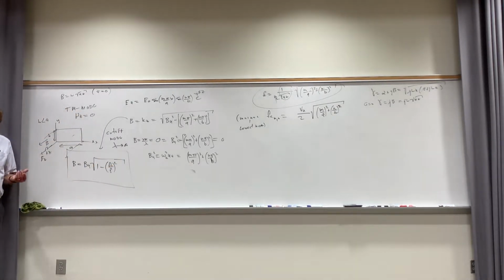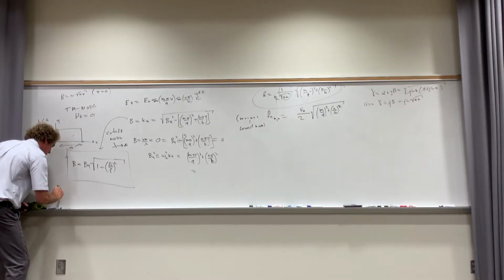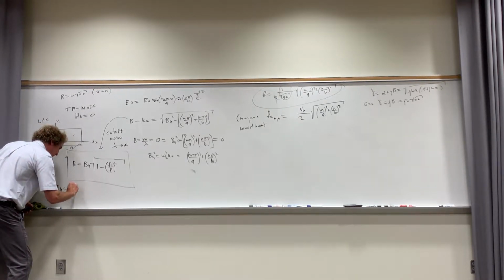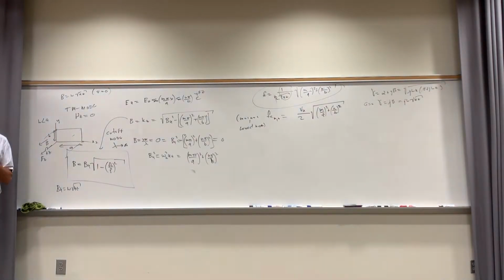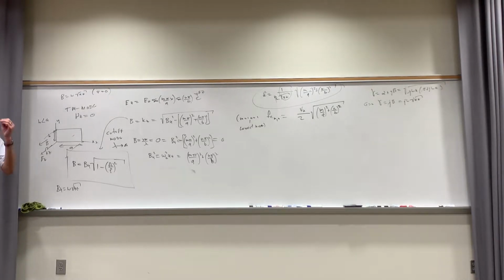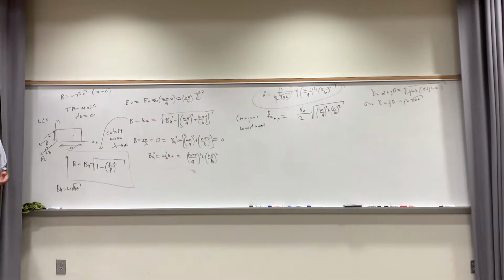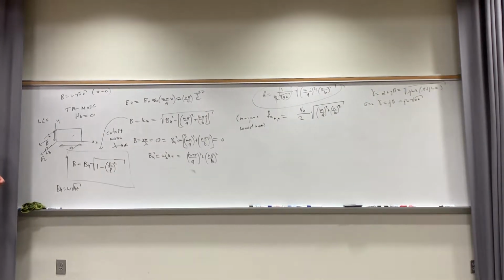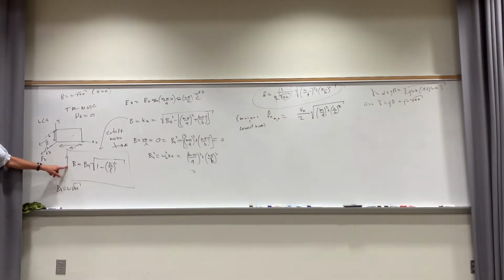Beta unguided is simply omega times square root of mu epsilon. That's all it is, and that's the mu and epsilon associated with what the waveguide contains, the inner part of the waveguide. It's usually air, but it doesn't have to be. It can be filled with a high pressure gas. You can fill it with argon if you want high power and you don't want the electric field arcing in there, so you put a gas in there that has a higher dielectric breakdown strength. But that's beta. And FC has to do with the mode number. The 1,1 would be the lowest for TM. All right, class?